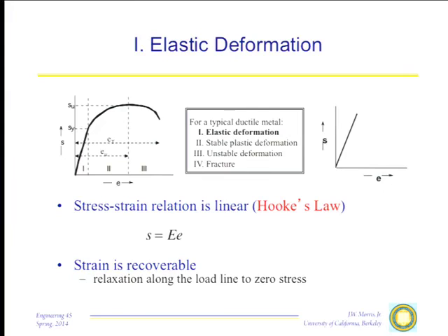I won't go into it in this course beyond just the two things, but in fact, the complete stress in a material is a second-order tensor, 3 by 3. I have 3 directions in which I can pull. I also have shear stresses, which can operate in 2 directions on each surface. So there are a grand total of 9 possible components of the stress. The stress has to be symmetric. Only 6 of them are independent, but basically this is a 3 by 3 tensor. The strain is also a 3 by 3 tensor, 3 perpendicular extensions and 6 shears, as I'll show you in just a minute. So the real elastic equation relates a 3 by 3 stress to a 3 by 3 strain. That means, of course, only 6 stresses, 6 strains are independent. That means I have a total of 81 elastic moduli, of which a maximum of 36 are independent. So in the most general case of elasticity, you're dealing with a rather complicated world.